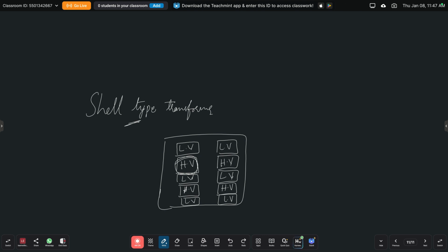Such subdivision of windings into small portions reduces the leakage flux. The higher the degree of subdivision, the smaller the reactance. In the sandwich coil diagram, the top and bottom coils are low voltage coils.